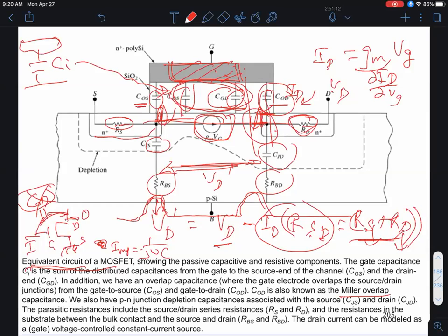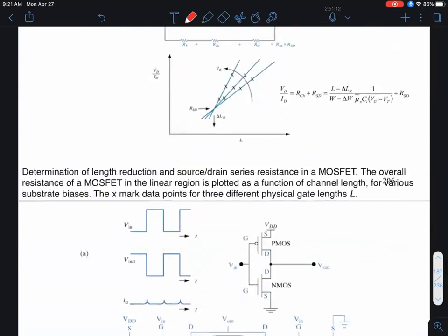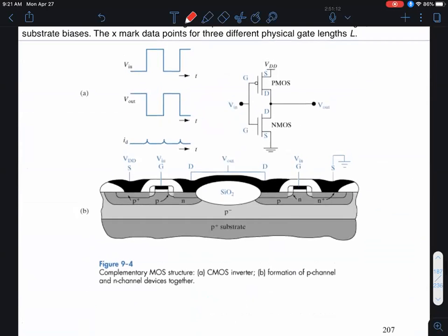Yes, it'll go down, because basically the VT is very high, right? Now you're depending on fringing fields from the gate turning the transistor on, so you cannot afford to have any underlap. This is called an underlap situation. So you want some overlap, but not too much, because that would increase the Miller capacitance. So the question is, how do you have your cake and eat it too? Let's discuss that. That brings me to the final part of the discussion of MOSFETs.